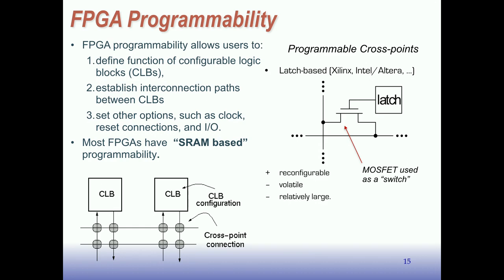In the boards in the lab, we don't do that. We program the FPGAs from a file, so some software sends the bits over a USB cable to the FPGA to program it, right? Which is the mode for debugging. But once it's debugged and you're going to embed that in a product like a scooter or something, as soon as you turn it on, you want the program to go into the FPGA. So that's one thing there.